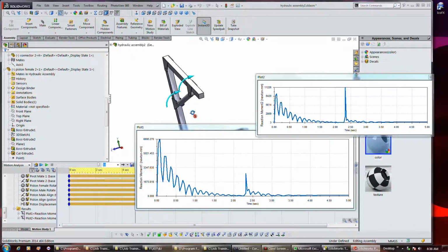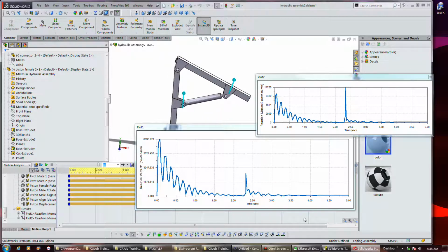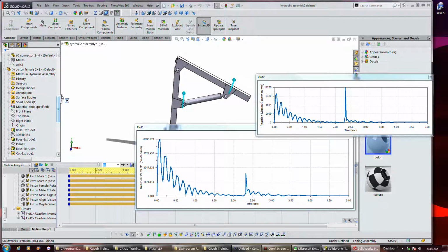Why would they be pointing that direction? But anyway, if they're calling some of these joints redundant, then again, that shows you that whenever possible, use mechanical mates if you know that it's going to be used in the simulation, because that's kind of the whole point of the tutor. They're telling you that mechanical mates or other mate types need to be carefully considered if you're going to simulate it, because for some reason it'll produce weird results.